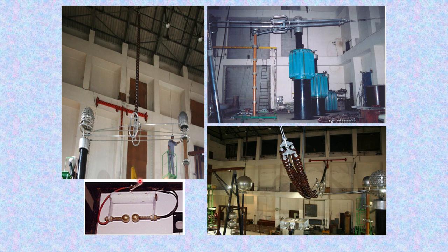So, the breakdown voltage across each spark gap is measured for the entire string, and the values are noted, and finally the distribution is found out. This helps in proper design, to check whether the corona control rings, the arcing horns, or other arrangements used as grading rings are properly designed and grade the entire string.